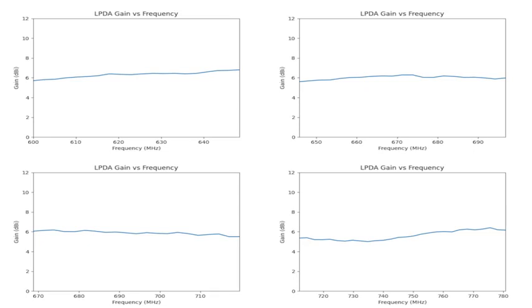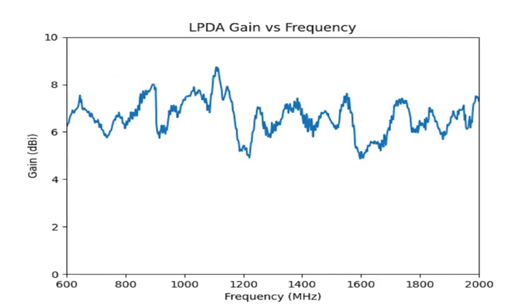The first 4 LPDA gain graphs can be seen where the computer determined a valid region for each one, with some overlap between them. This was to ensure the entire region is included. All 14 different valid regions were then grouped, with overlapping areas averaged out, to prepare this final graph of the gain of the LPDA antenna throughout the desired frequency range.